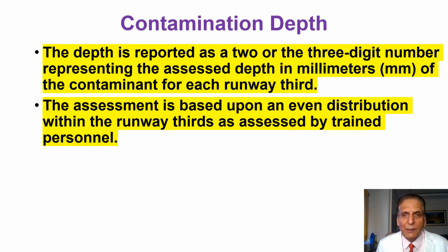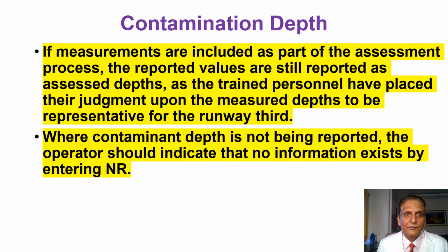The assessment is based upon an even distribution within the runway thirds as assessed by trained personnel. If measurements are included as part of the assessment process, the reported values are still reported as assessed depths, as the trained personnel have placed a judgment upon the measured depths to be representative for the runway third. Where contaminant depth is not being reported, the operator should indicate that no information exists by entering not required, NR.